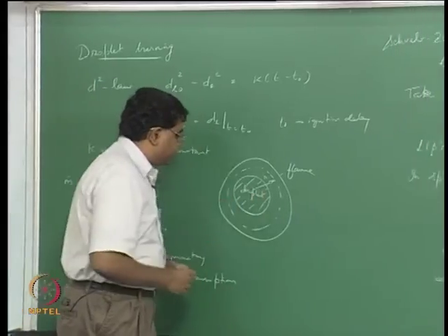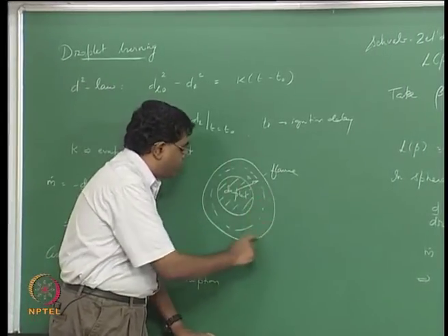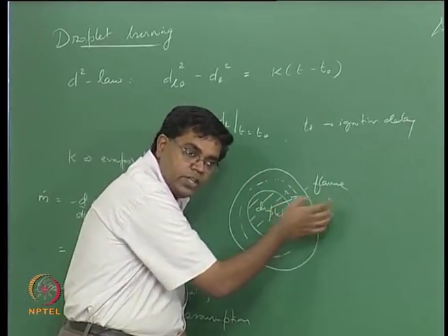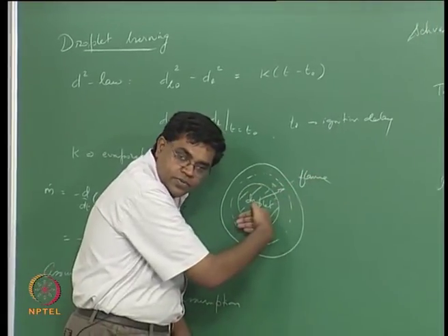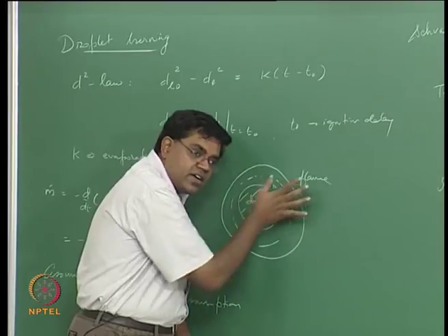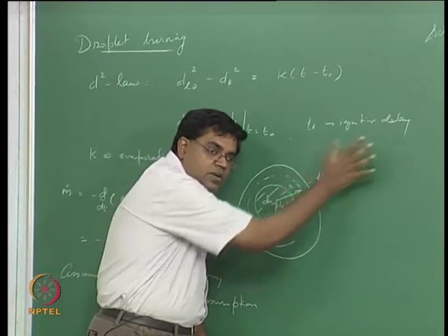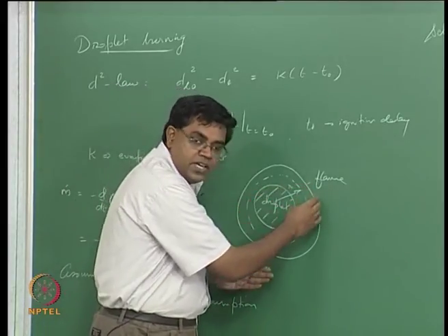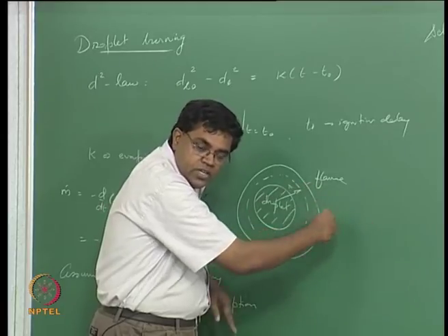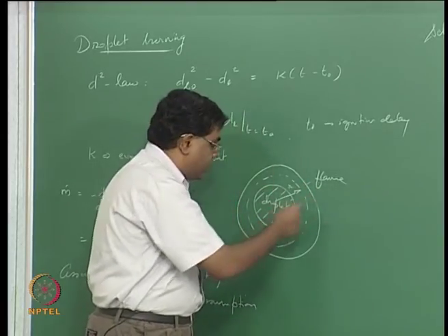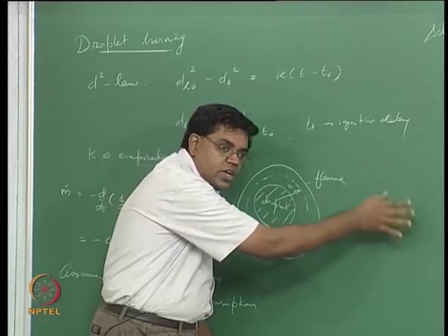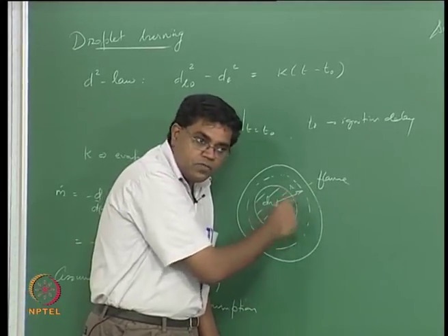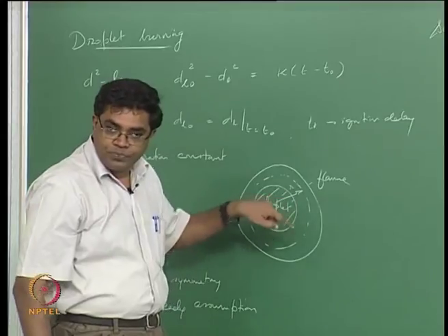We could think about it like that. So what we would expect is, as the products are being formed at this flame, they are at a high concentration relative to the neighborhood, and therefore they would have a tendency to diffuse, right. So they would diffuse inward against the current in this case, as well as outward, right. When they diffuse in, and of course the temperature is also going to be at its peak at the flame, and it's going to come down on both sides, and while it goes out there, it's going to match the oxidizer temperature in the far field, but it's going to match the surface temperature of the liquid, which could be like the boiling point of the liquid, right.